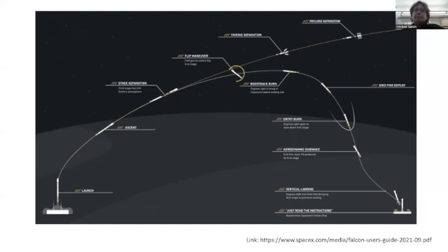And the way that looks is you'll have a lot of acceleration in the axial direction for sure. But you know that a change of direction is also a type of acceleration. So your payloads that are in the nose cone of the rocket, in addition to seeing axial accelerations, are also going to see a variety of lateral accelerations during the launch.